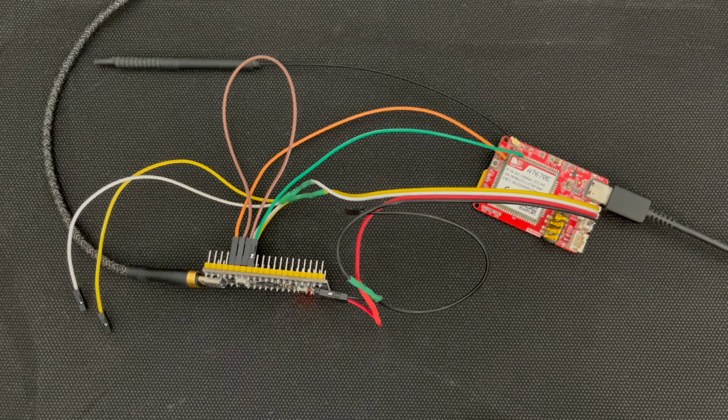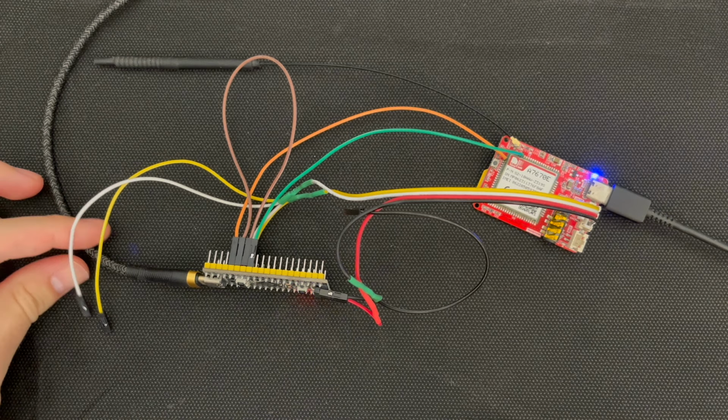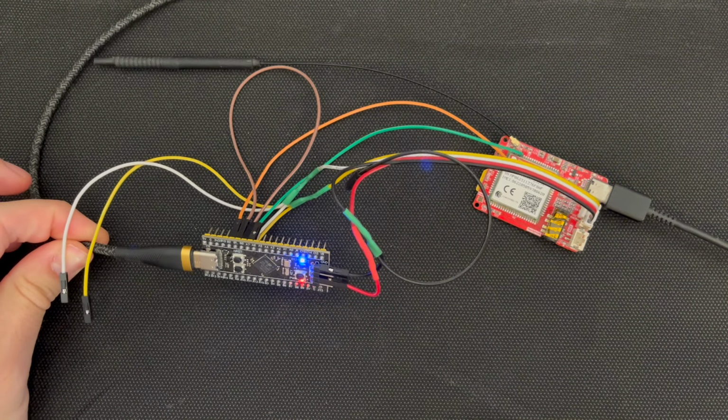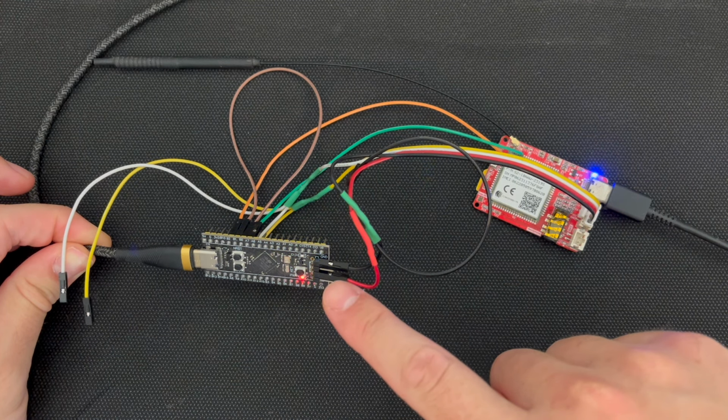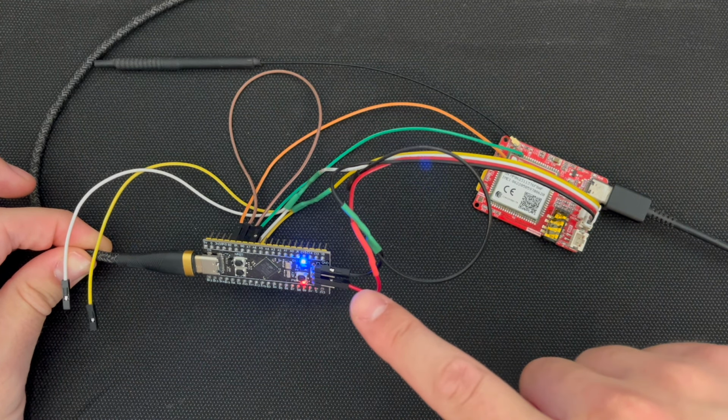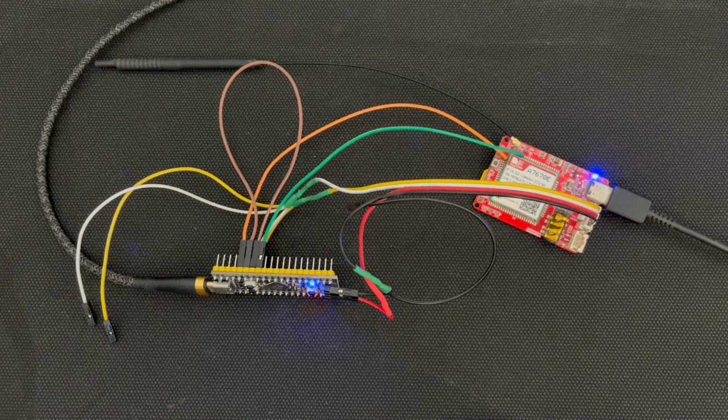Just going to bring this down to the bottom again, and if we go over to our hardware right now, as I stated earlier, you will see there is a blinking LED now. On our module it is doing 250 milliseconds on and 250 milliseconds off as a heartbeat, and that is for the code that we have just added.